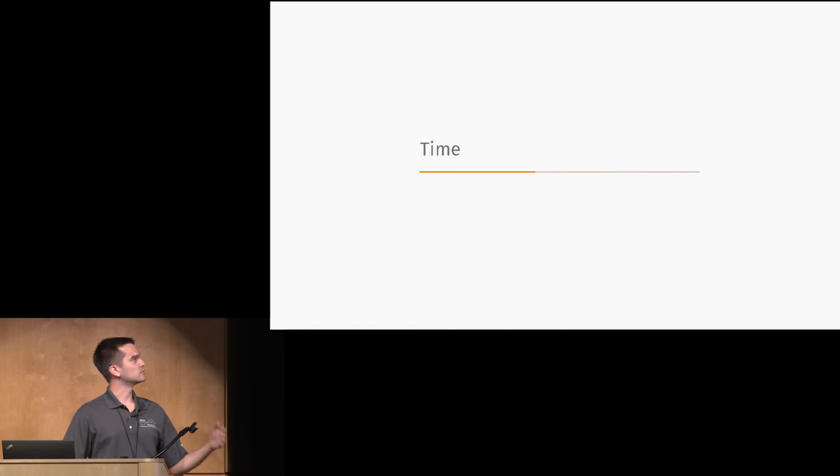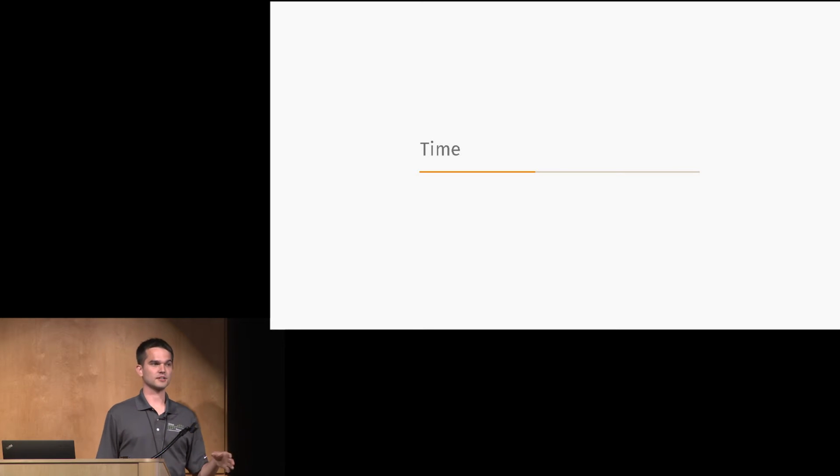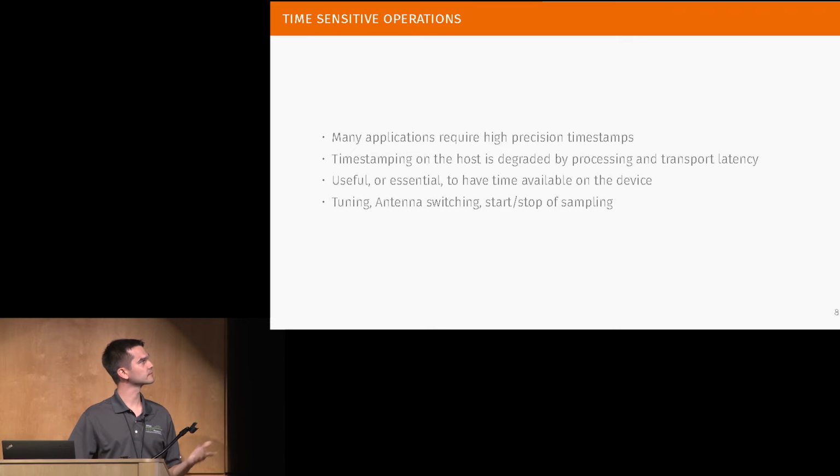So that covers frequency synchronization. And the basic principle there is just if you supply an external reference, then you can have that shared between different SDRs, and so they'll all be at the same frequency, and you're translating that accuracy onto all the radios. And if they drift, they'll drift together because they're all sharing that same frequency reference.